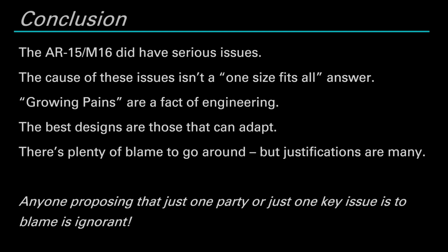The largest number, in terms of sheer number of failures, came from this bolt bounce issue in full auto. Fixing the buffer and making it a good, sturdy design, one that is sort of the standard for buffer designs that we use today in our modern AR-15s, was necessary for the rifle to overcome that aspect of its immaturity. Those issues are certainly interlinked, and while they do have a little bit of crossover into some of the other issues, all of the postulation that the powder changed the dwell time and the cycling time, and that's what made the failures to extract happen, isn't actually backed up by the facts and the data.